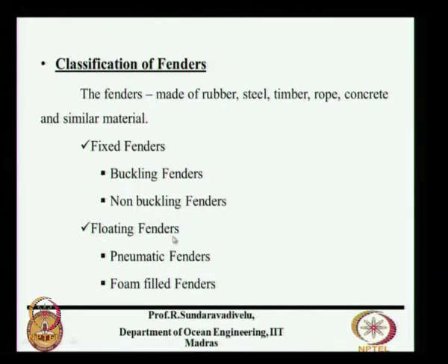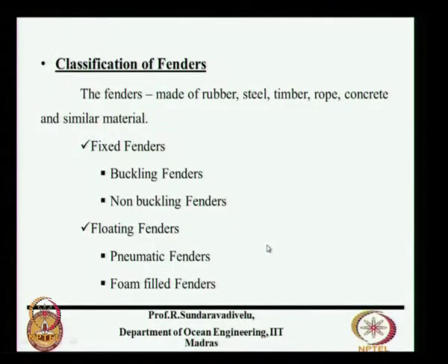Two advantages, one is the weight of the fender need not be transferred to the structure. The second is we do not have to have a big frontal board, because the floating fender, if it is low tide level it goes to the low tide level, if it is high tide level it goes to the high tide level. So, that is the purpose of the floating fenders.